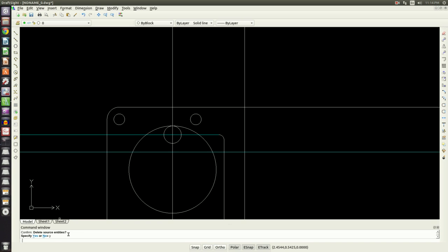Now we have our 2-inch radius. Now there's a couple other ways you could have done that. You could have gone ahead and mirrored this line down, 0.8 down, and then found this center point down here. But that was a lot of extra drawing that you didn't need to do. I like this method. It's quick, it's concise, and it used a couple commands that we haven't talked about yet.